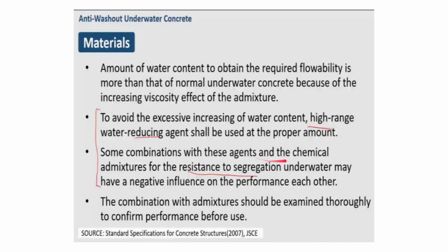Some combinations with these agents and chemical admixtures for the resistance to segregation underwater may have a negative influence on the performance. The combination with admixture shall be examined thoroughly to confirm performance before use.